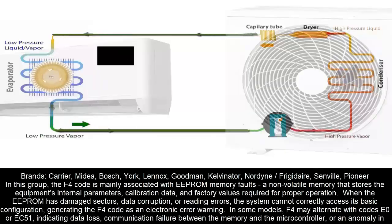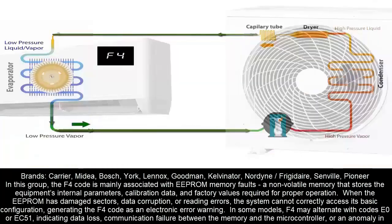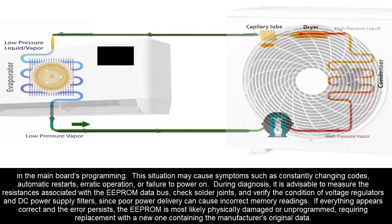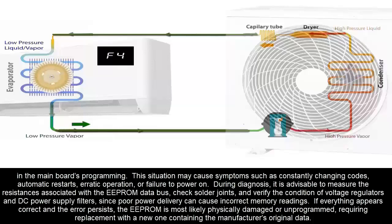In some models, F4 may alternate with codes E0 or EC51, indicating data loss, communication failure between the memory and the microcontroller, or an anomaly in the main board's programming. This situation may cause symptoms such as constantly changing codes, automatic restarts, erratic operation, or failure to power on.